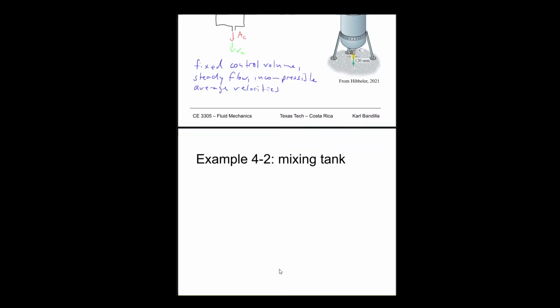equation here, our continuity equation, right? So the original version of this would be, that should be a partial d dt over the control volume of rho times dV plus integral over the control surface of rho times v times dA equal to 0. Now we just said that we have incompressible flow or incompressible fluid, which means that our rho is going to be constant, so we can just divide it through and we don't need rho anymore.